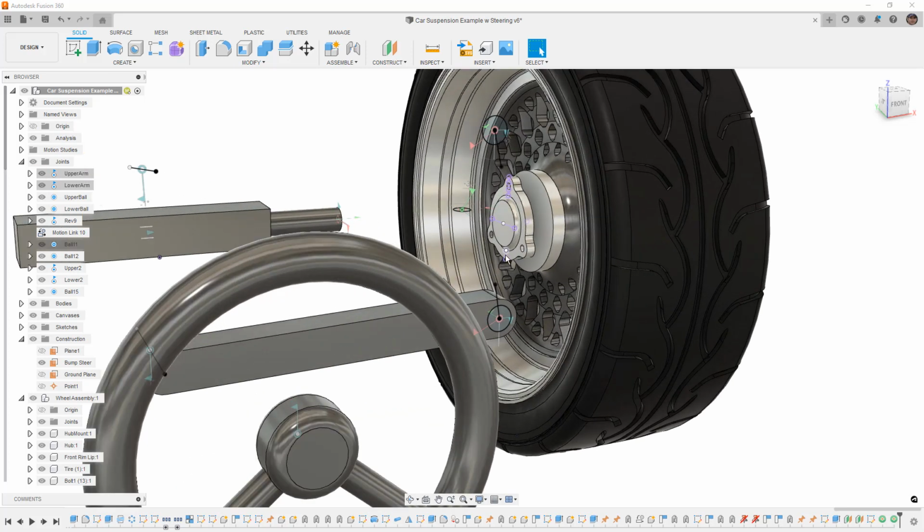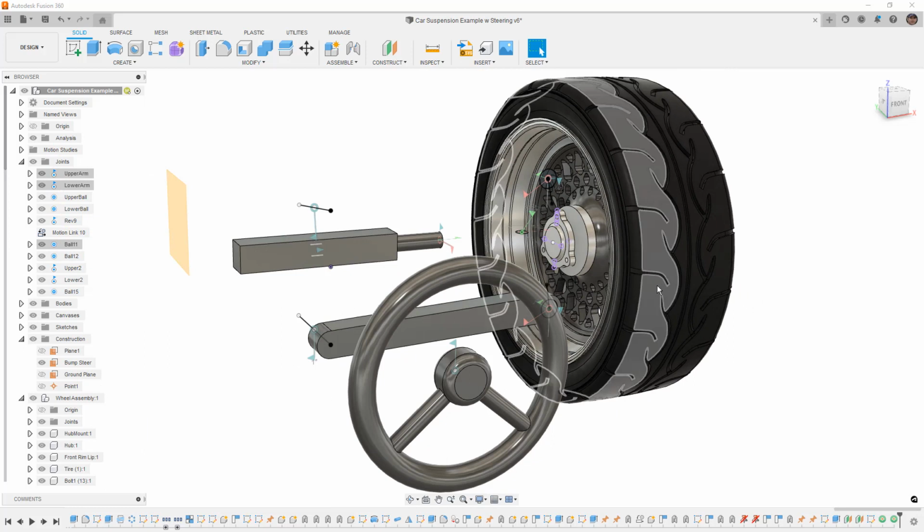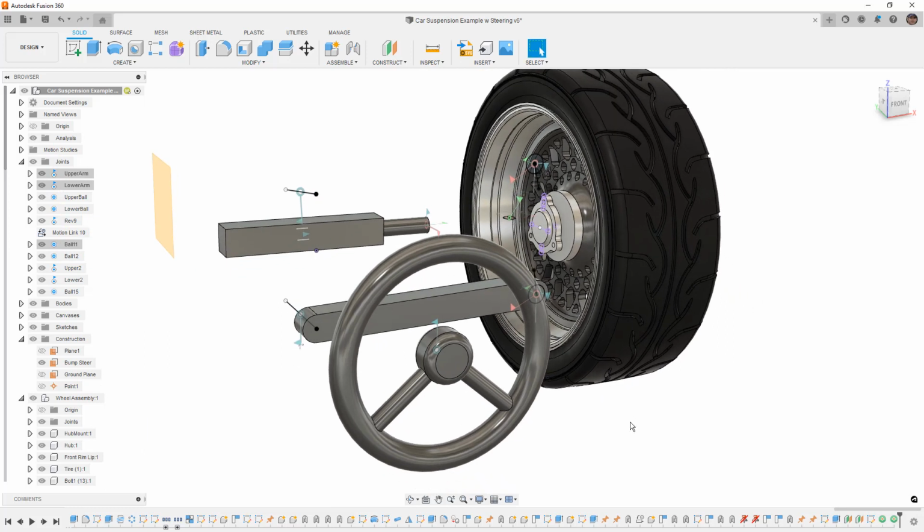Again, if you have sketch points, those are perfectly fine. All we're really looking at is the delta, or the difference between the starting and the end point. So as long as you have two points that you can track, it doesn't really matter what those values are, because it's a difference that we're looking at. And the last thing is just sort of brute force, all right? So this design would have been better had I had a shock setup where I could alter the linear distance of that slider joint.